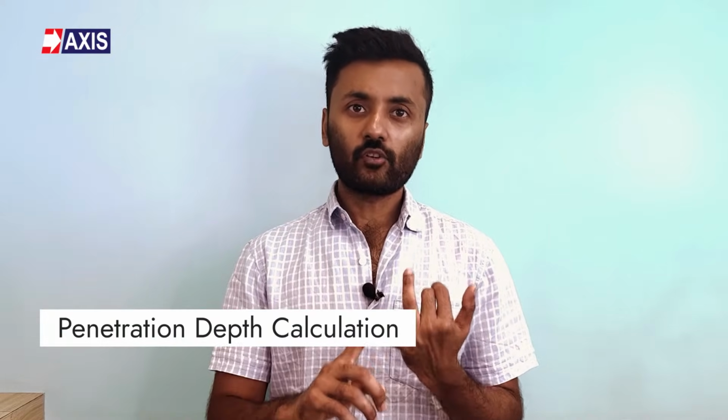In this video, I will be discussing what the rolling sphere method is, its radius and outer zones, air termination calculations using the rolling sphere method, and the penetration depth calculation, which is an important consideration for lightning protection design. So let's start by understanding the need for such methods.